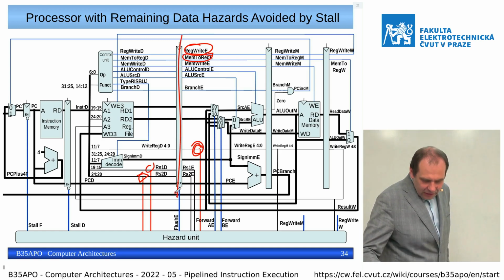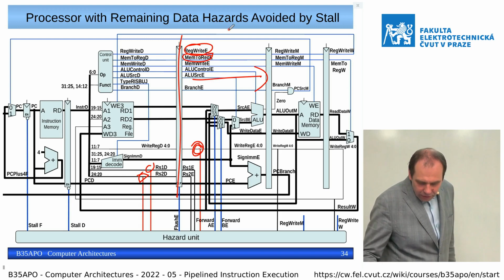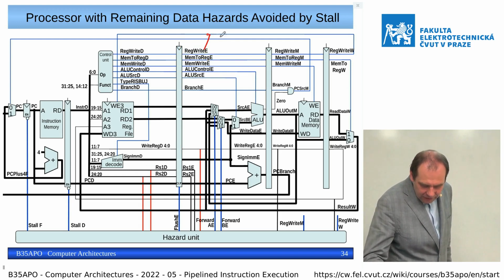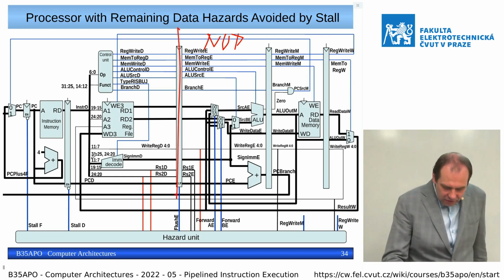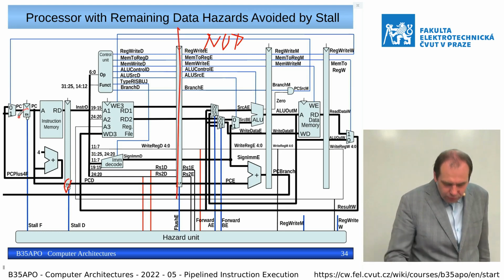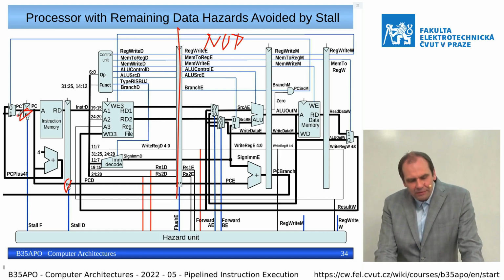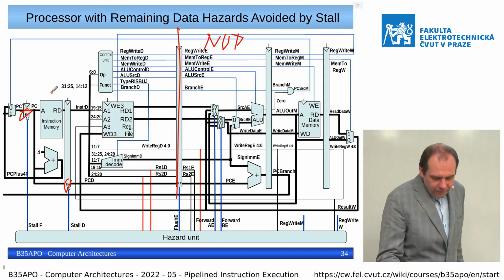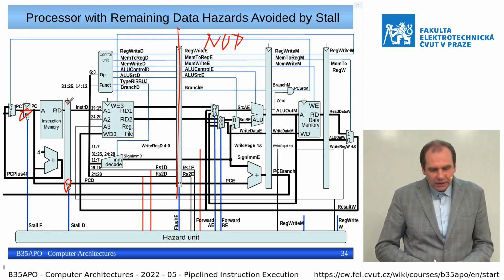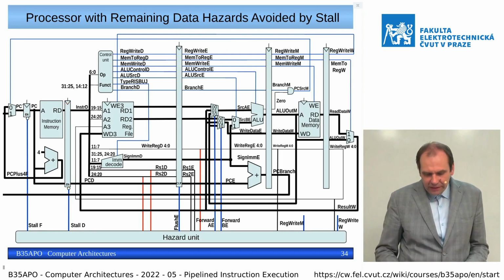So on the next clock cycle, this instruction advances here, and on this stage a NOP instruction is generated, and we stop the clocks to those two registers. Basically we stop the advance of the program counter, and we stop the store of the fetch from the instruction memory. And this way we resolve the problem.